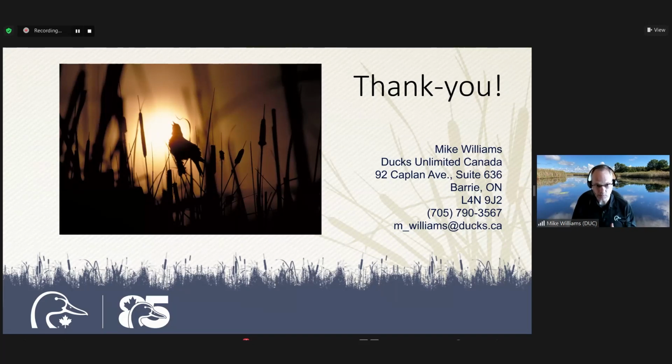And our experience has been that when we try to use a native blend of just warm season grasses, over a few years, the site does get invaded by cool season grasses anyway. So we find that a blend of cool and warm season grasses seems to hit that right balance of getting something greened up early in the spring to prevent erosion and prevent weeds from growing. And then in midsummer, when those cool seasons senesce, the warm seasons kick in, and you get that real nice height diversity. So we haven't concocted the recipe yet, but it will be specialized for the site.